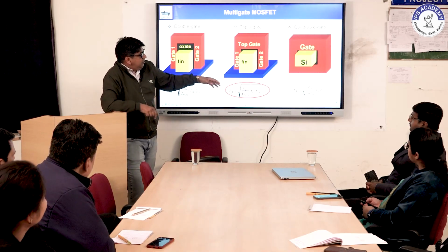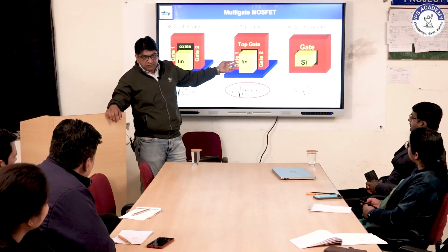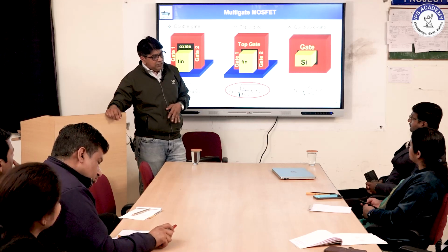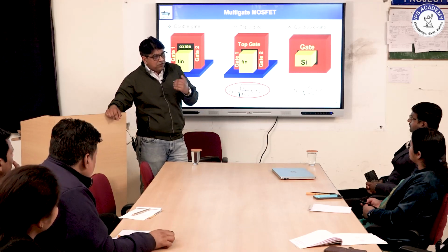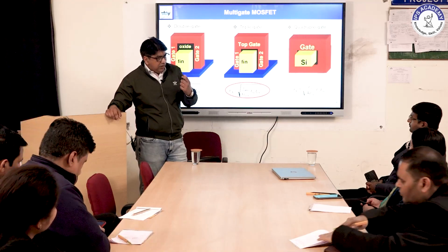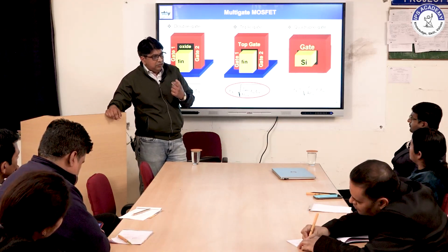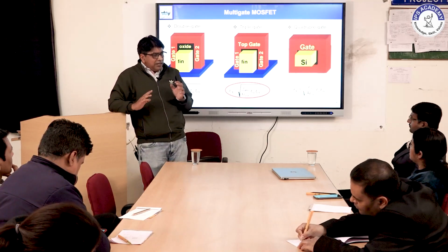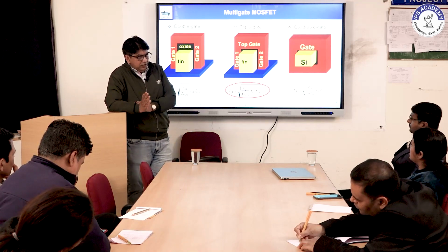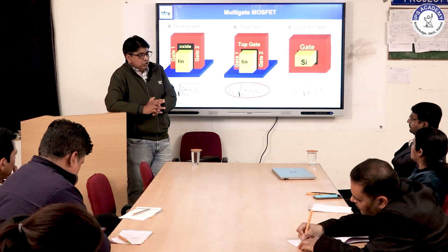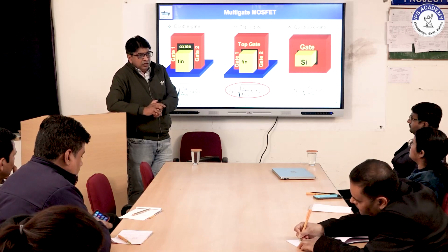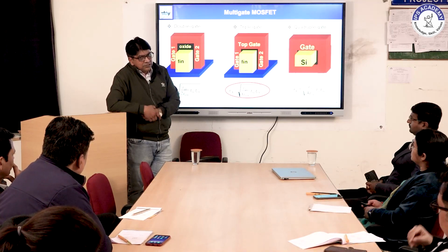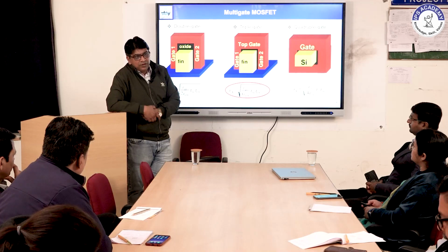After 5 nanometer, FinFET technology is again not suitable. The reason is that below 5 nanometer, the fin aspect ratio, the ratio of width and height, creates a problem. That is a scaling limitation. Also the pitch from one fin to another, the distance, we are not able to scale down. So when we go to the next advanced node after 5 nanometer, the problem of gate controllability started again.